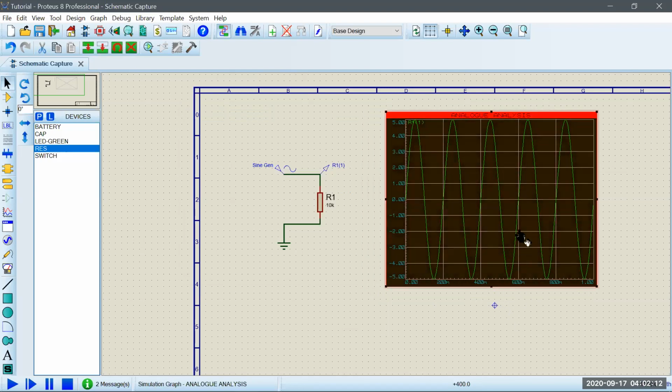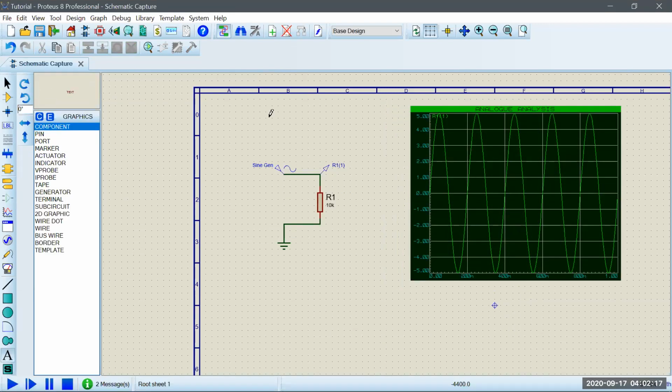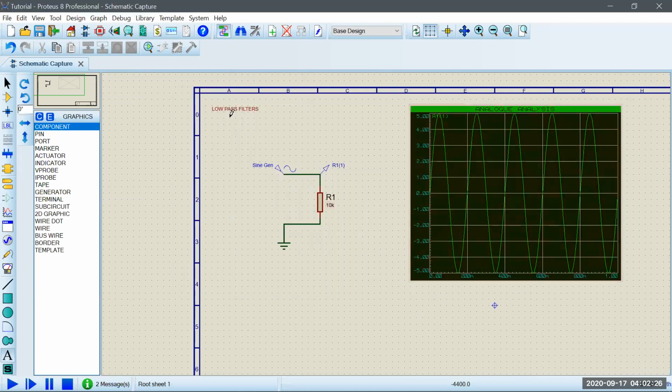To make filters, I think the most basic passive filters are low pass filters. Now, there are lots of ways to make low pass filters. You can make use of RLC, RC, RL. But in this case, for an example, we will be using RC, resistor and capacitor. So how do you make a low pass filter? Basically, the circuit looks like this.